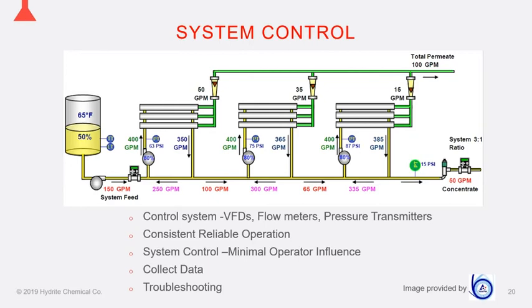If we went to the Dead Sea, our osmotic pressure would be higher and we'd need a different pumping system to create that fresh water. Because the Dead Sea has higher salt content, it has a higher osmotic pressure. So basically what's happened is we have a higher osmotic pressure on loop 2, but we still have the same driving force, which is our baseline pressure, still 15. So if we wanted loop 2 to perform the same amount of permeate coming off it at 50 gallons a minute, the same as loop 1, we would have to install another pump to get that baseline pressure higher to force those molecules through.